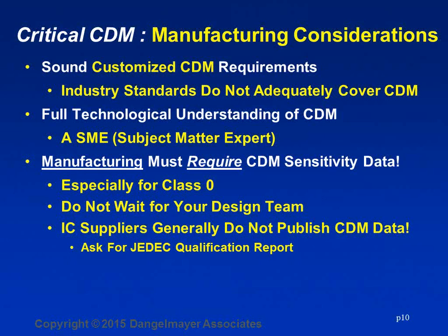And unfortunately, IC suppliers generally don't publish the CDM data, which is particularly frustrating. So when you go after it, you'll find it's not in the data sheets and difficult to locate. If you ask for the JEDEC qualification report, it is there and required for JEDEC qualified devices. So that often makes it a little easier to obtain the data.